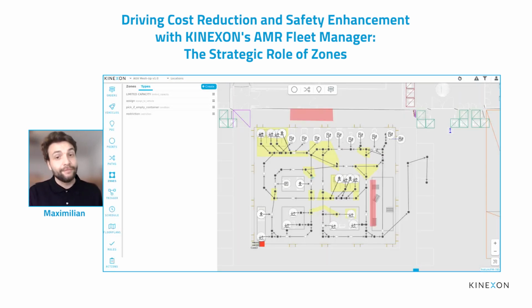Because in the end, a good system, yes, the graph model works well in the VDA 5050. But the more we think in the future, the more the robots will have more and more autonomy. And the AMRs will also make more decisions based on that. And that's always linked to zones. That's linked to areas. And they will detect, are there three areas to drive? Or should I take route A or B? And exactly for that kind of logic, zones are crucial because they don't just follow a straight line, but they might do obstacle avoidance on the way, or decide if they should go left or right in the long run, based on those costs, for example, or on obstacles and so on.